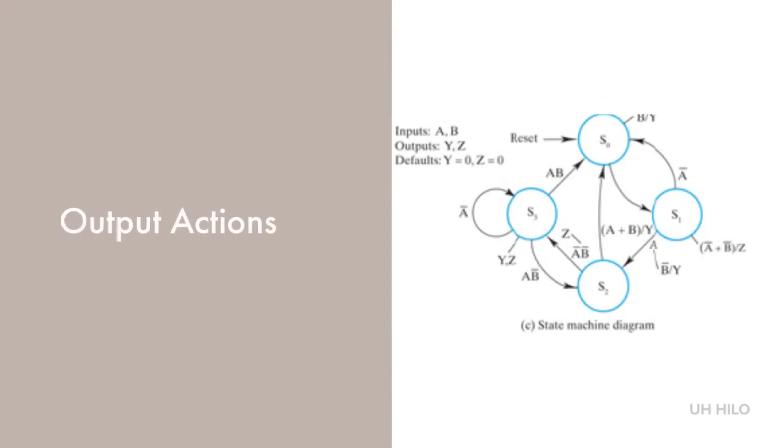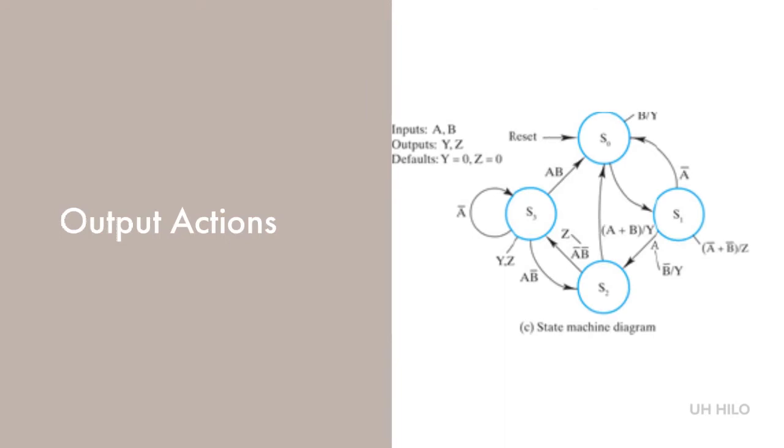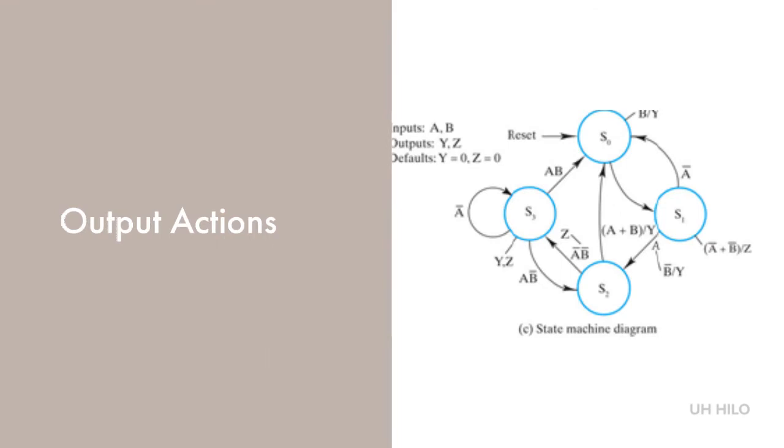In a given state, an output action occurs if it is unconditional, that's a Moore, or TCI and its output condition OC is equal to 1, or TCD and its transition condition TC is equal to 1, or TOCD and its transition condition TC and output condition OC are both equal to 1. Any output action may be simply an output variable. It's also possible to have variables that are vectors with values assigned as the output. The final element that can appear on a state diagram is the binary code assigned to a state.